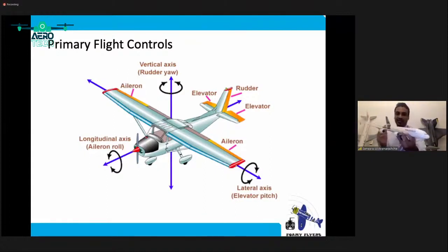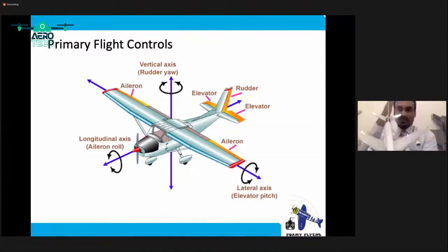So what does the rudder do? Okay, so similarly, the rudder is here. You can move the rudder surfaces left or right. When you turn the rudder to this side, the front moving air will hit that rudder surface and push the aircraft towards this side, right? Does it make sense? So when it is turned like this, it will push this way, and to the other side, it will push this way.